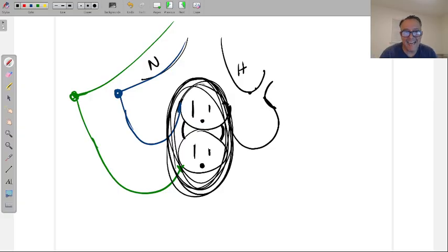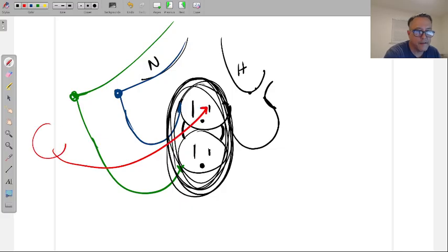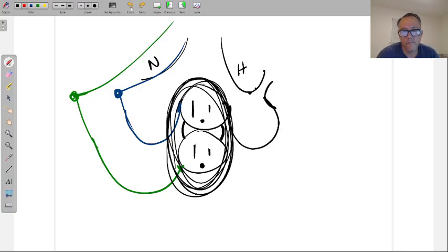There shouldn't be any arcing unless you have something plugged into this and this thing is in the on position. You can have something plugged in. If it's a lamp, turn the lamp off. Or better yet, just unplug everything.